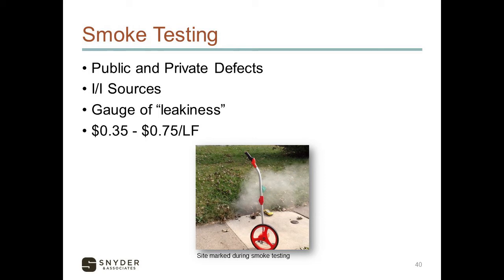We pump smoke into the sewer, and there will be a field crew that will walk pipe or the adjacent area and try to identify if they see any smoke above ground and mark those with flags. And then we'll take survey equipment out and get a GPS location on those to try to understand from a mapping standpoint what those locations might be attributed to.